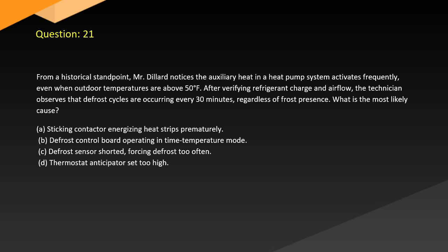Question 21. From a historical standpoint, a technician notices the auxiliary heat in a heat pump system activates frequently even when outdoor temperatures are above 5 degrees. After verifying refrigerant charge and airflow, the technician observes that defrost cycles are occurring every 30 minutes, regardless of frost presence. What is the most likely cause? A. Sticking contactor energizing heat strips prematurely. B. Defrost control board operating in time temperature mode. C. Defrost sensor shorted, forcing defrost too often. D. Thermostat anticipator set too high.